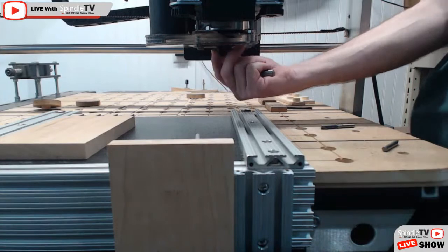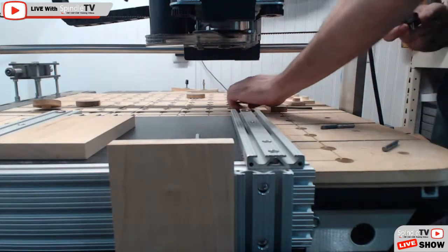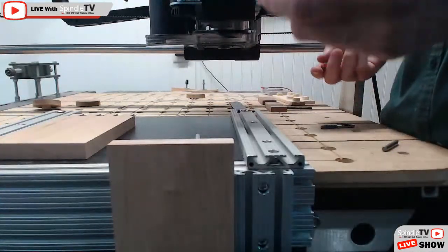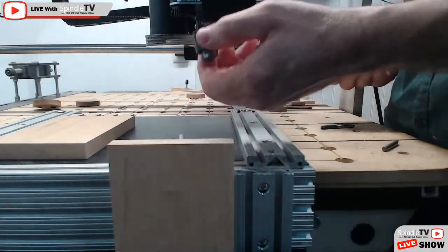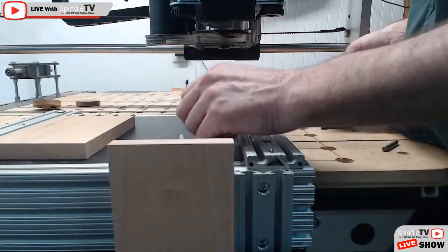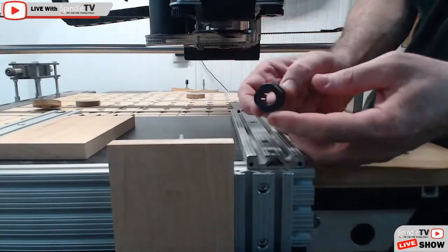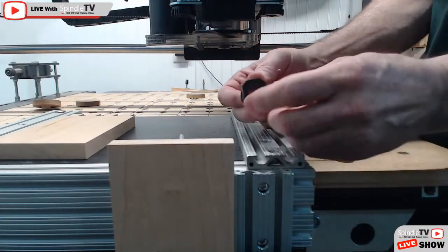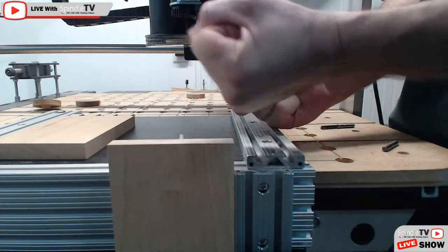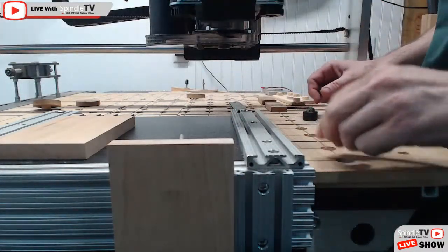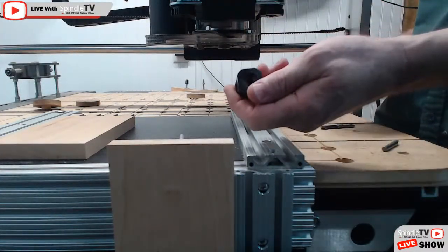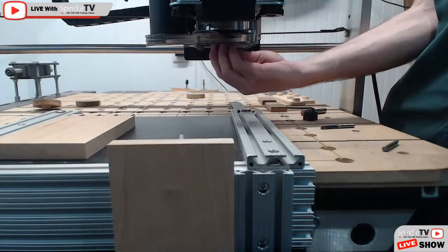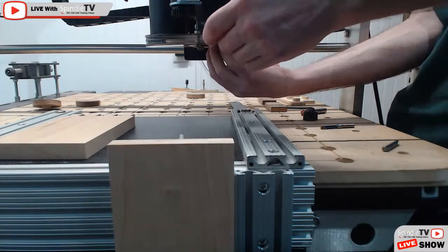By the way, all digital wood carver owners, when you're changing your bits, well, everybody really should do this, whether you have a spindle or a router or what have you: take your collets all the way off during your bit change. Tap out the dust and buildup, because as dust builds up in these fins, it can pack in and keep that collet from gripping the bit. So you want to keep those tapped out and clean. You don't want any buildup in those collets. Hot tip of the day.